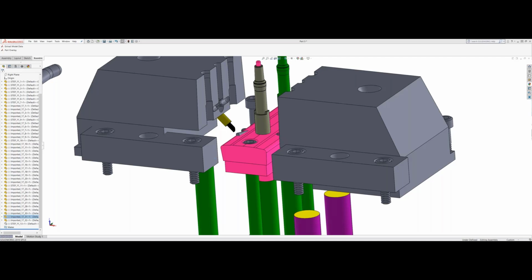It's a kind of a low level, looking at fill, sink, pointing out thick areas, potential areas of non-fill. And then, again, just more upfront, the better we know about the project. That way we can, kind of, where we can't gate, what are the critical requirements of the part, the tolerances, all that's going to be dictated by that. But yeah, we try to do a full DFM and mold flow analysis on all the parts.